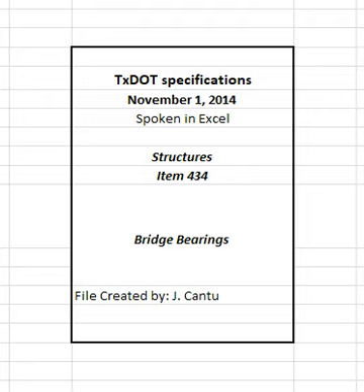3.1.1 Markings. Mark the bearing type on the surface of each bearing as shown on the plans. The marking must remain legible until placement in the structure. Permanently mark, in addition, laminated bearings with manufacturer's name or trademark, lot number, date of manufacture, month, year, and direction of slope. Place this permanent marking on a face which is visible after erection of the bridge unless otherwise shown on the plans.